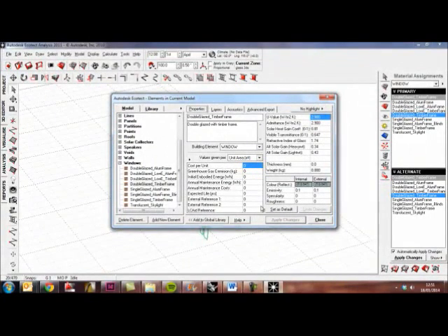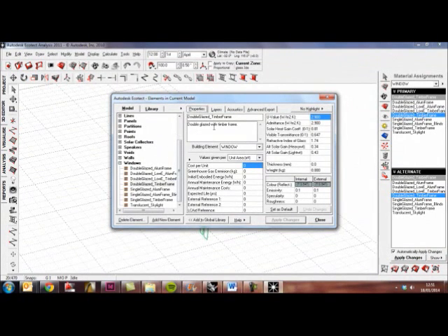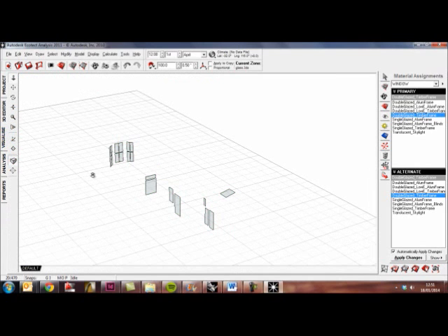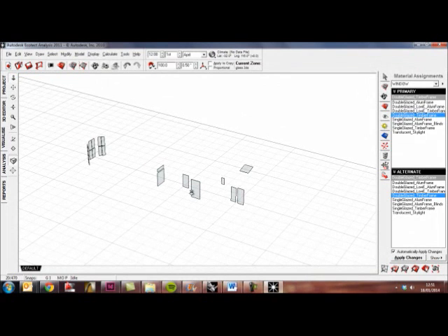Double click that. When I double click that, it gives me a whole load of material qualities which as we go in other exercises will become relevant, but for the time being the only thing I'm looking for is transparency, because I want to see inside the rooms in a visual way. So we're not going to say much about this other than it exists. And having set that material, when I go into visualize, I can now see through these windows.